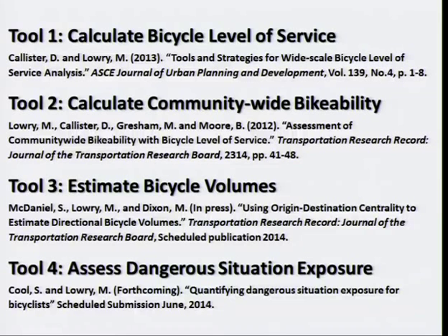So there's a whole different level in what they can handle in terms of counting at an intersection, which, by the way, goes back to why I think the critical thing is to get all those movements. I don't think I actually mentioned that. You could do a screen line where you just get 2 things, or you could do all 12 movements. For my tool, since you want as much data as possible, I think getting the 12 movements is right, but don't get any of that other stuff about male, female, helmet, no helmet, because it just complicates things.